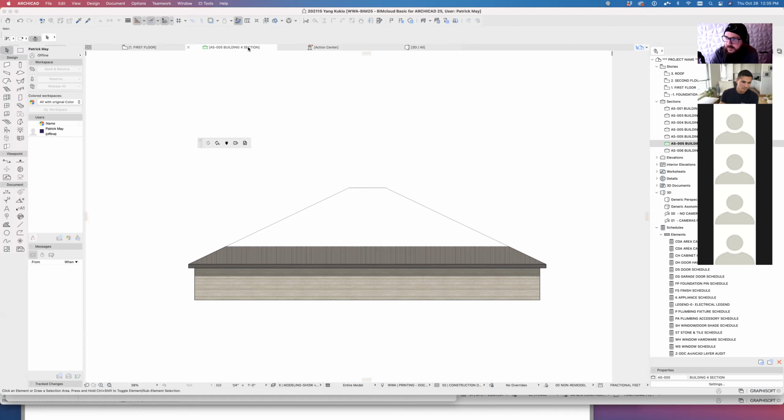I'm still running some tests, like I said, on the Twinmotion direct connect option. The preliminary tests on a really simple model were really promising. Matt and I actually looked at that together the other day. It's a pretty cool little feature that allows you to just basically live link the two. It obviously has some drawbacks: if you're trying to do some serious modeling in Archicad and that's trying to update in Twinmotion at the same time, it slows things way down. So you sort of have to know the workflow.